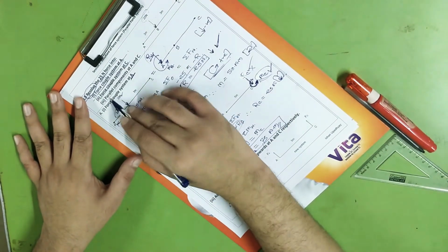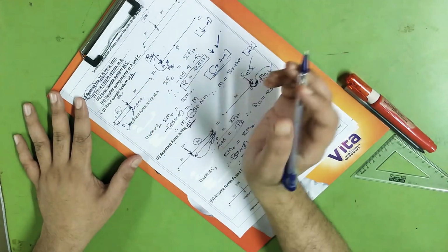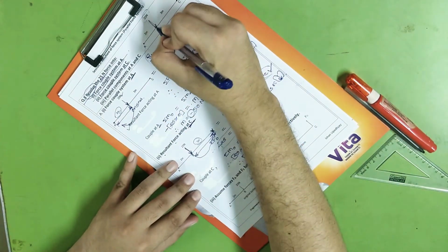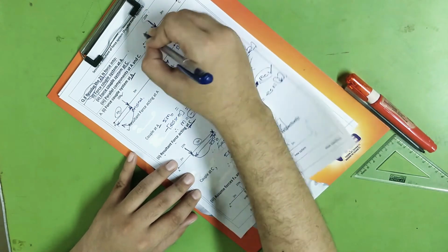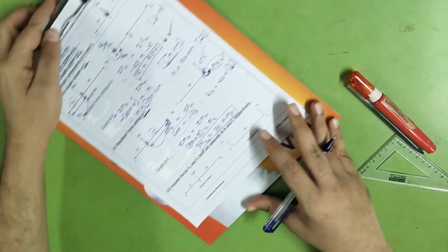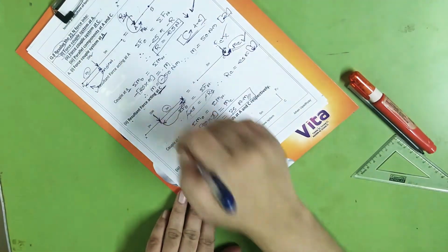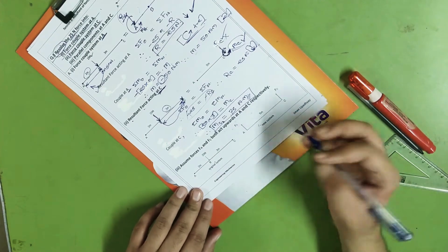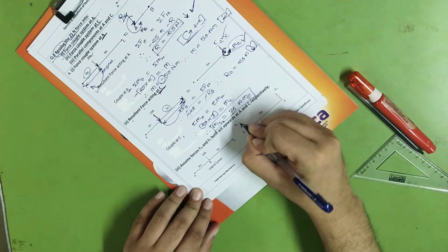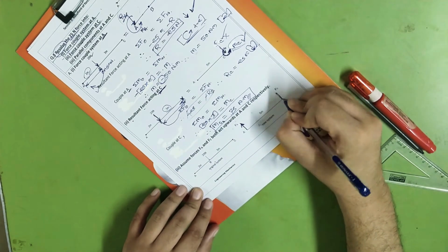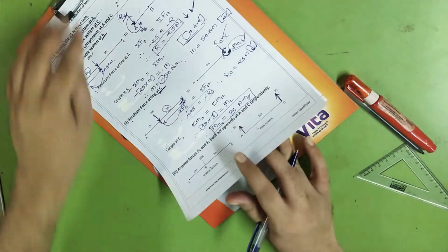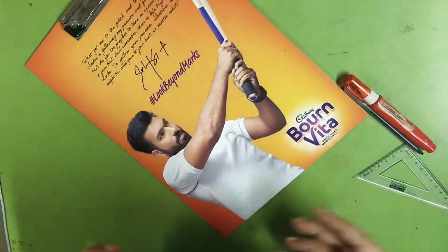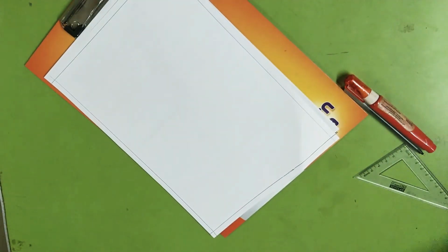Then we will go for the third, that is parallel components at A and C. So what I have to do? I have to resolve this 25 Newton of force into two parallel forces, one at A and one at C. So it's given over here. You can see that the original system is the same thing I have copy pasted here, and for the new one I have assumed FA and FC, that is force at A and force at C, in upward direction. Now I have to solve this third case so that I can get the values of FA and FC. Now to solve this, what will we do?